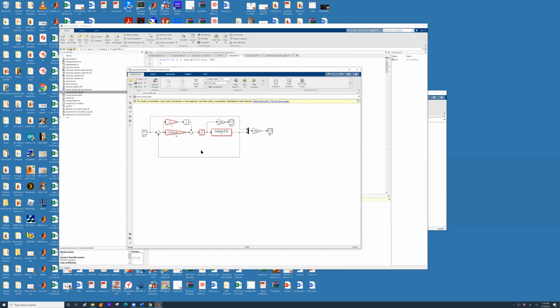Now let's look at how this loop is implemented. If you don't have any disturbance, course can be approximated to heading because there is roll and yaw coupling. So basically this course hold loop is exhibiting that type of coupling. This is the gain, which is the proportional gain. This is the gain of the integrator. This is the saturation block.